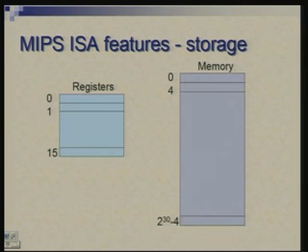That means, this is a range of addresses which can be supplied, but physically the whole space may not be filled. So, in a particular system, you may have, for example, 256 megabytes of memory. Okay. It means that rest of the space is empty and nothing is there. So, how much memory you physically have depends upon what kind of configuration you want to have. Okay. What is specified by the architecture is the maximum you can have.